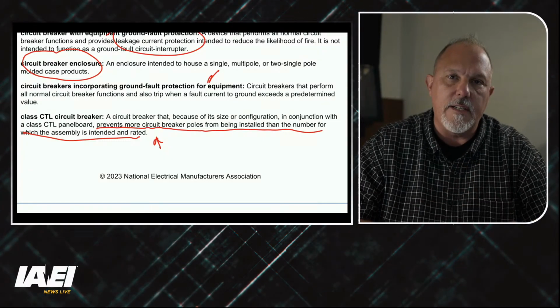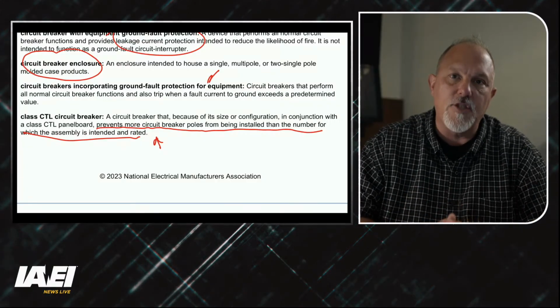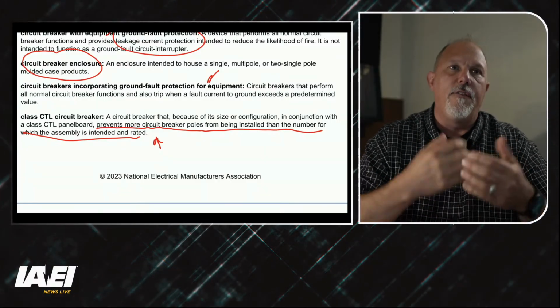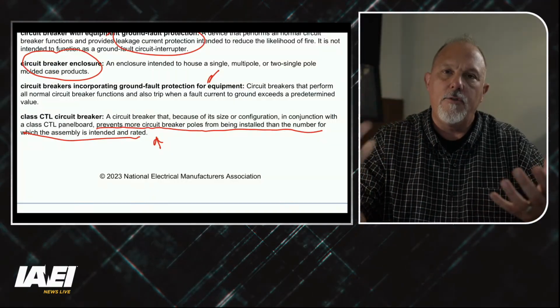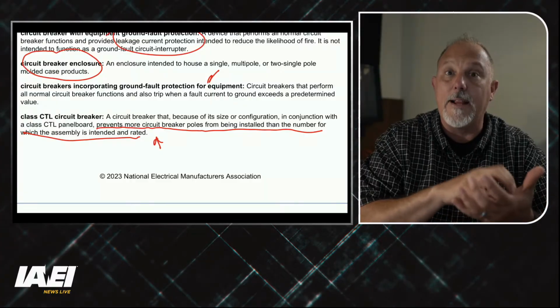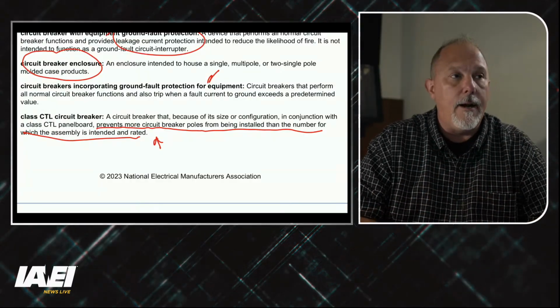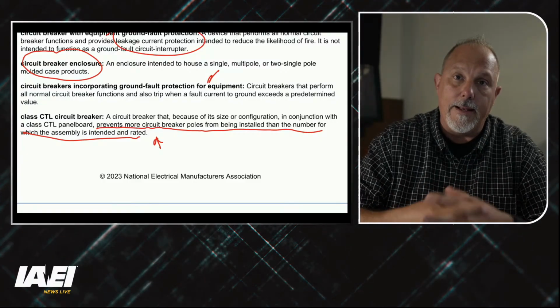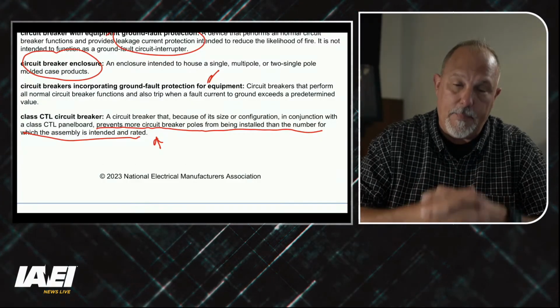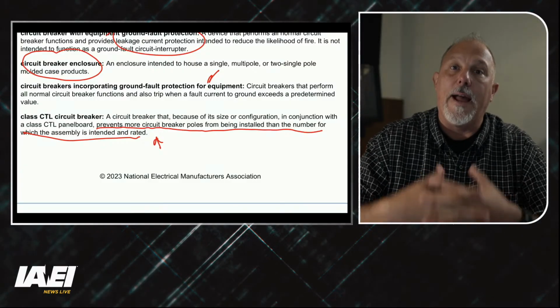You're going to put these devices in an enclosure, and they have to be able to match with each other. Not only the form factor on how to either plug or bolt or connect that circuit breaker onto the bus, that has to be in concert and listed and tested as a pair, but also other aspects of it.